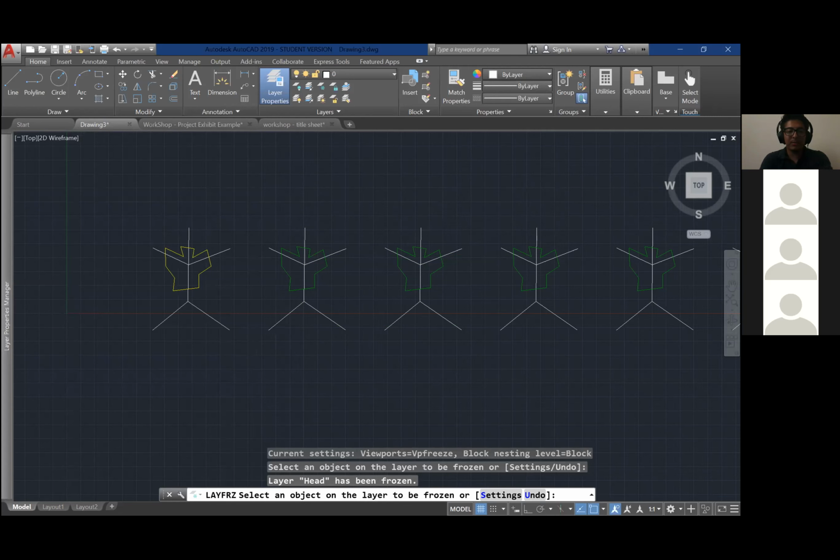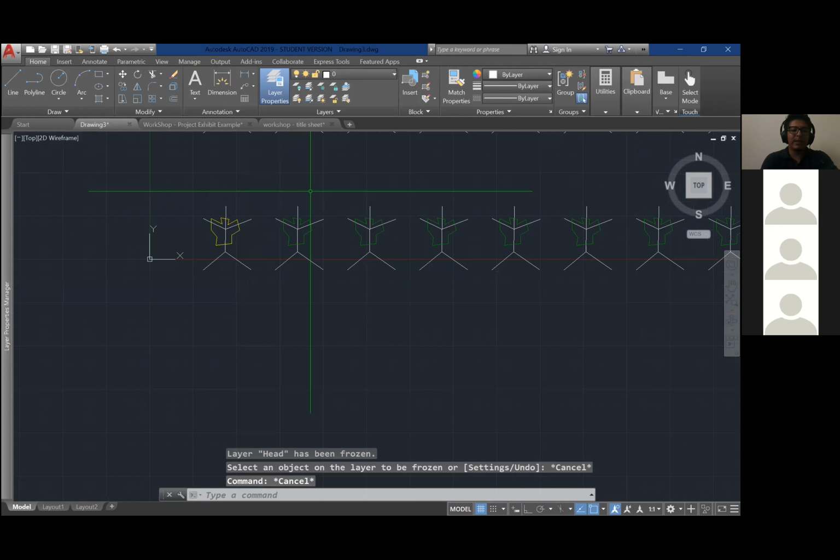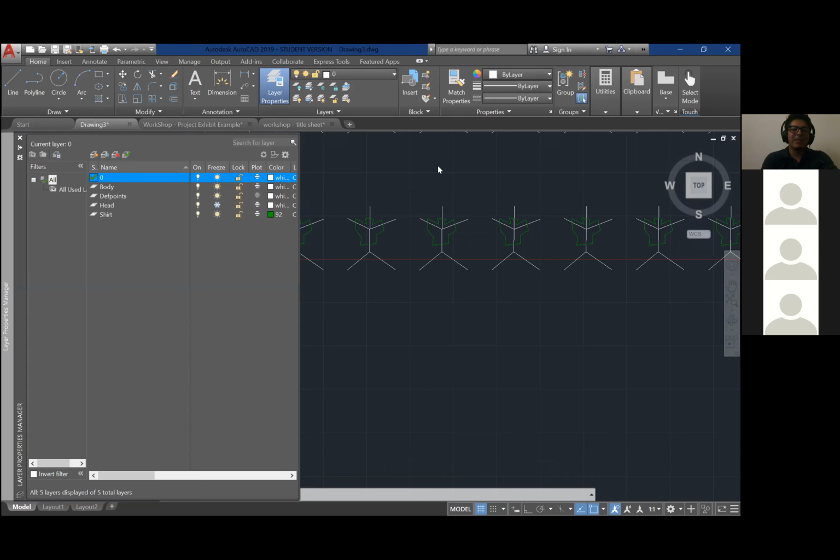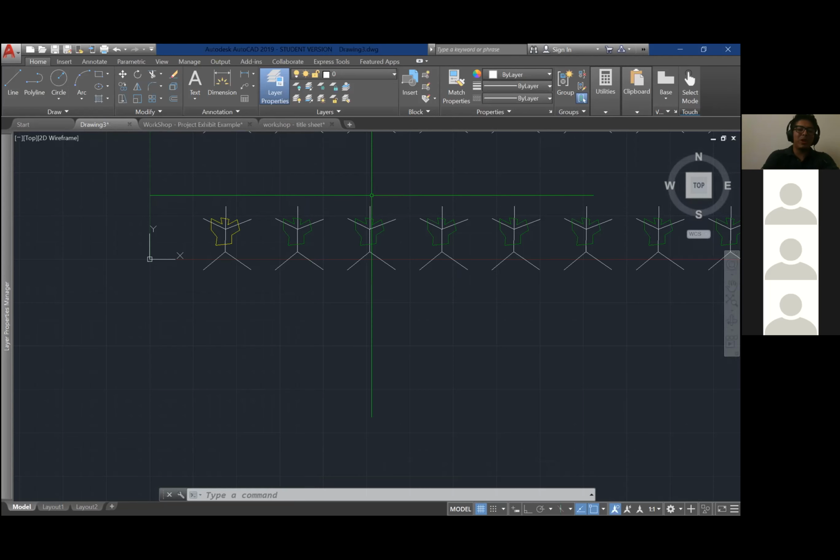This is kind of why I got in trouble for it too, because the other engineer didn't see a fire hydrant layer on here, and he froze it. And the layer I was drawing in had a bunch of other things in it, so when he froze it, he froze like half the drawing. So half the drawing turned off. Yeah, so you don't want to do that.